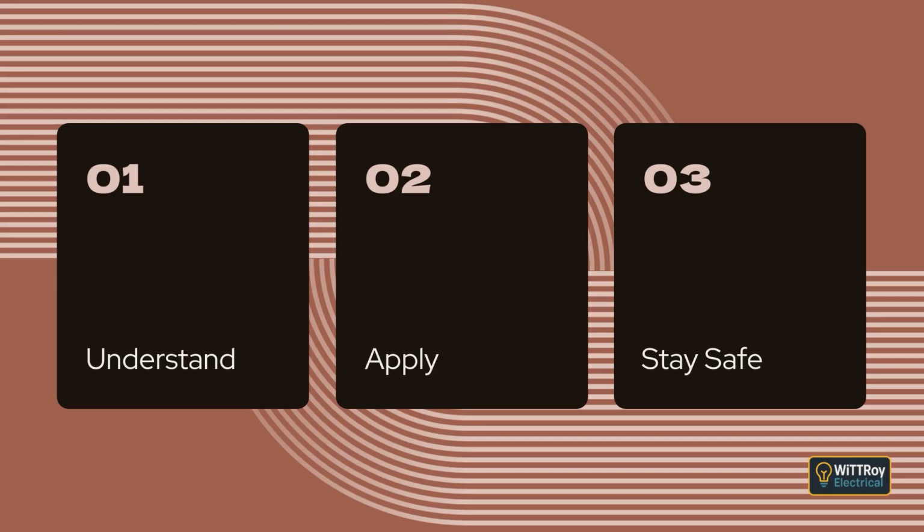Clause 2.5.7.3, General Supply Circuit Discrimination. Clause 2.5.7.3 deals with normal electrical circuits. Just like the earlier clauses, the goal is to minimize loss of supply. Protective devices must be arranged so that downstream devices trip before upstream devices.